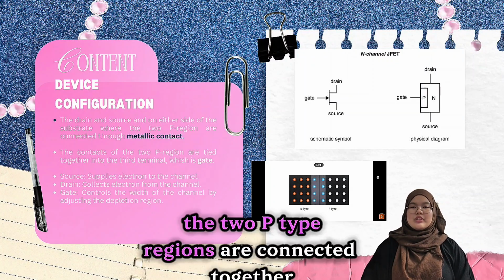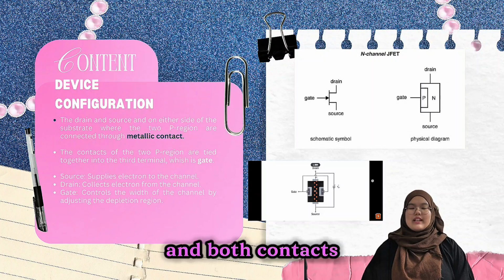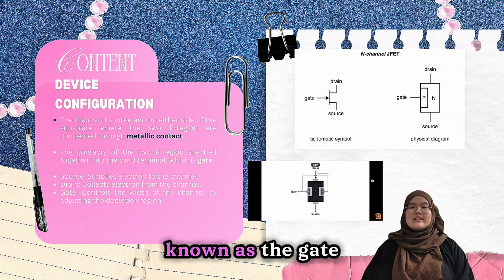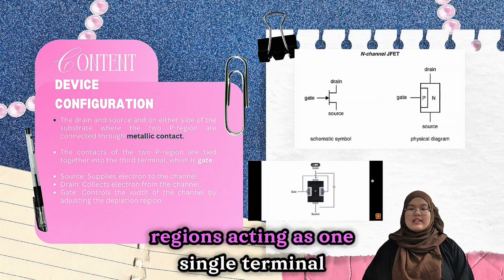The two P-type regions are connected together internally. Metallic contacts are made to these P regions, and both contacts are tied together to form the third terminal known as the gate. This means the gate is actually made from two P regions acting as one single terminal.